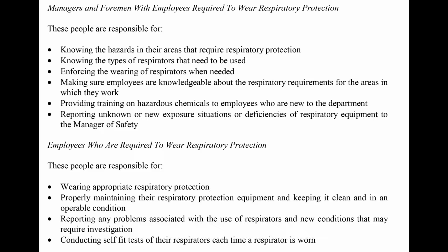Employees who are required to wear respiratory protection. These people are responsible for wearing appropriate respiratory protection, properly maintaining their respiratory protection equipment and keeping it clean and in operable condition, reporting any problems associated with the use of respirators and new conditions that may require investigation, conducting self-fit tests of their respirators each time a respirator is worn.